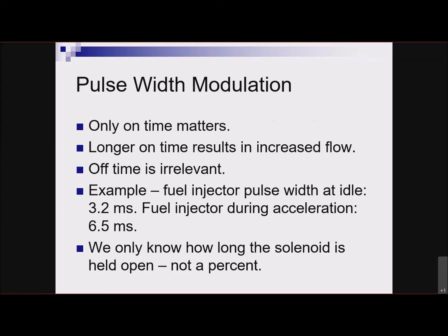Think about it. If I'm going 70 miles an hour and I back down on the accelerator pedal, right? I don't need to deliver hardly any fuel, but the engine's probably spinning pretty fast. So the amount of time that the injector is off is going to be really small because the intake stroke is going to come around again really quickly.